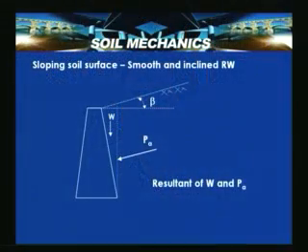From there, we will be able to calculate the active earth pressure thrust due to soil with an inclined backfill surface. Suppose we have a retaining wall which is smooth but inclined. Initially, the wall face we are always assuming is vertical and smooth, and the backfill surface is horizontal. Suppose you have a typical masonry wall, and assume that it is smooth. In such a situation the earth pressure is the resultant of the weight of the soil in that wedge portion and the lateral thrust exerted by the soil.